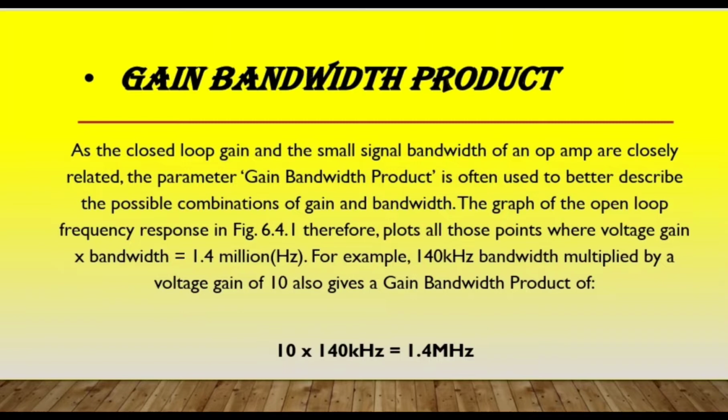So note the bandwidth indicated by the gain bandwidth product applies to small signals, but when large AC signals are involved, especially signals with fast rising and falling edges, the bandwidth may be further reduced by the slew rate, then the power bandwidth becomes more relevant.